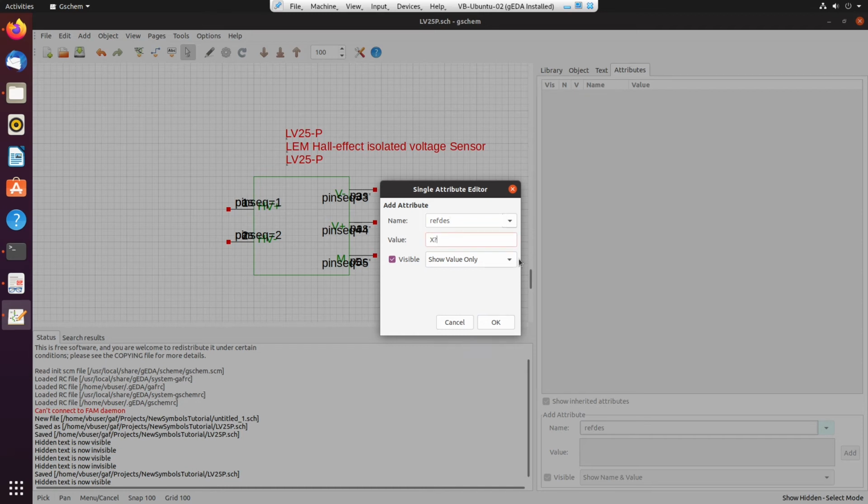If it starts with a C, it assumes that it's a capacitor, and so on and so forth. If it sees an X, then it means that it's a subcircuit. So it expects a subcircuit definition or a netlist, a SPICE definition for this component, which is typically how we would use this if we wanted to simulate it. If you are simulating ICs, the common usage is to use U as the reference letter. So we can use U for now, or we can use X, either is okay for the moment.